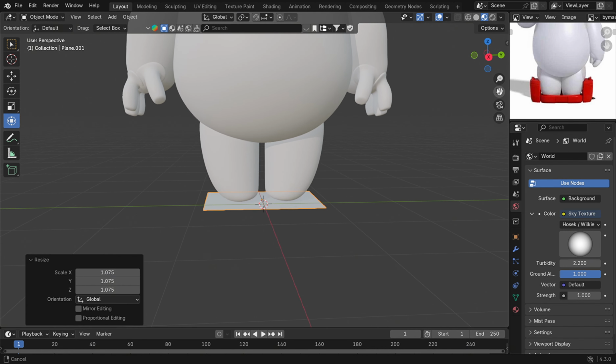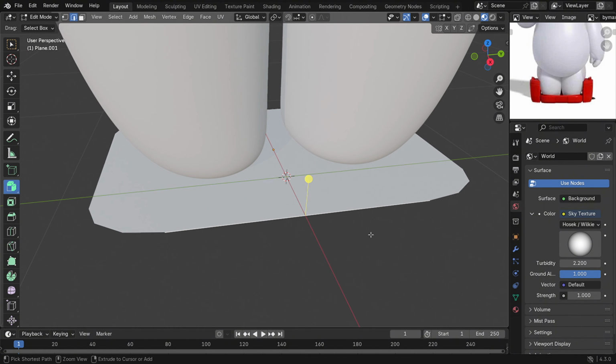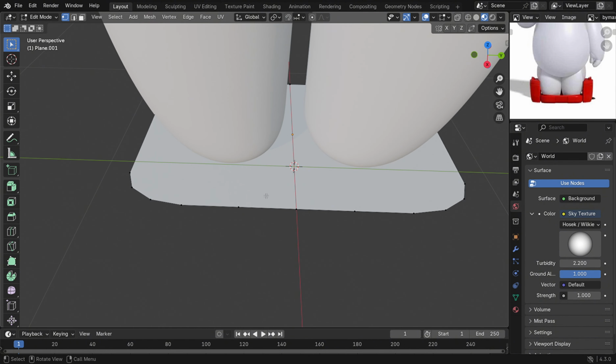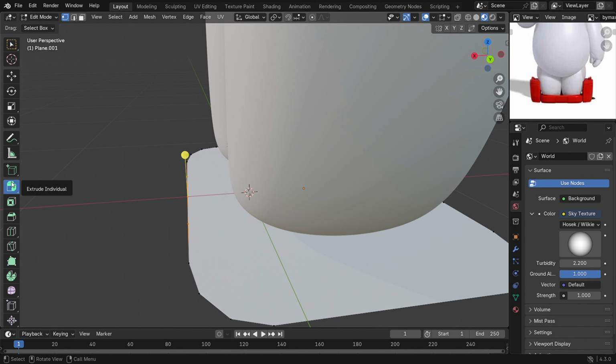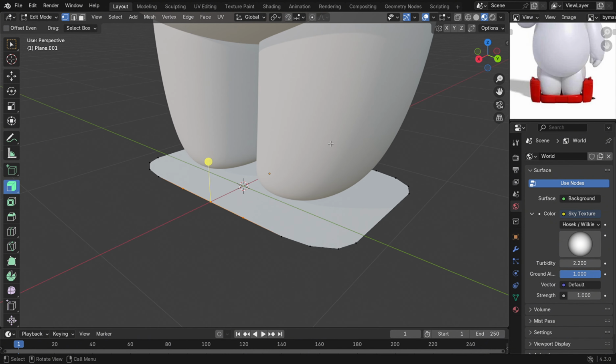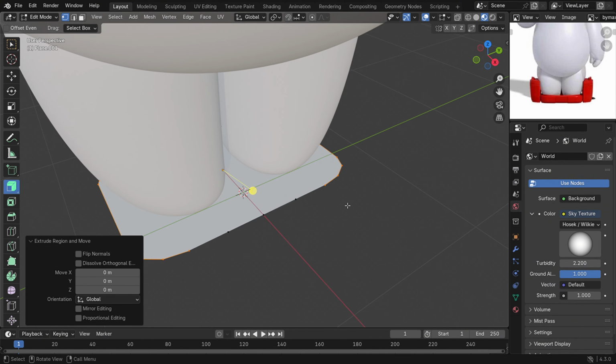For the surfaces we divided, we extrude outward, select the corners of the plane, extrude along the z-axis, and apply bevel operations for sharp edges. We'll also apply a solidify modifier for thickness and finish this part.